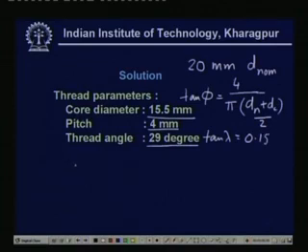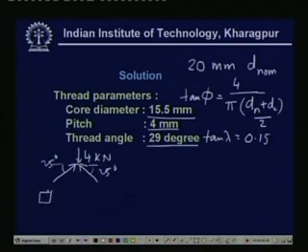Then from this given data, we will have to calculate the force on the nut. That is again done by elementary static analysis. If you consider 4 kilonewton here, then you get this was 25 degree and again this is 25 degree. We have to calculate the force over here, then this force is again transferred to this nut from this side, and we have to calculate the net force.